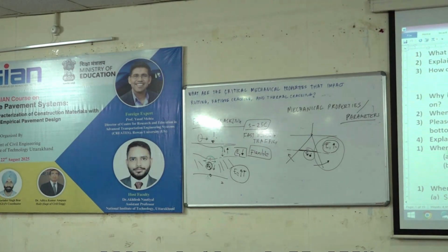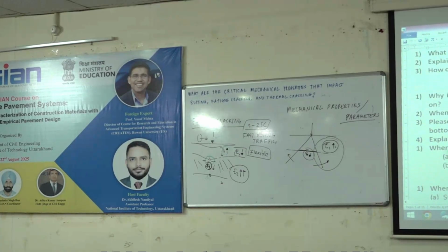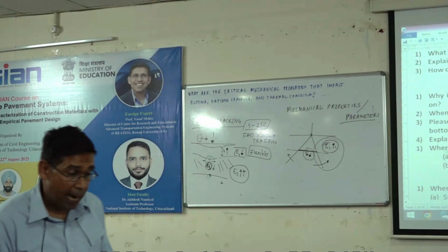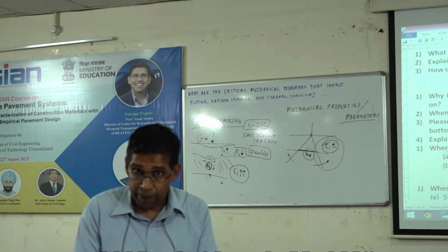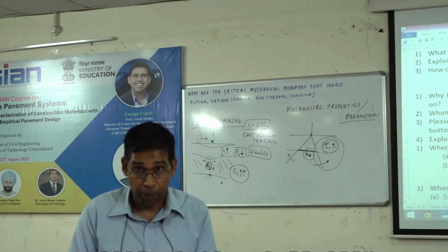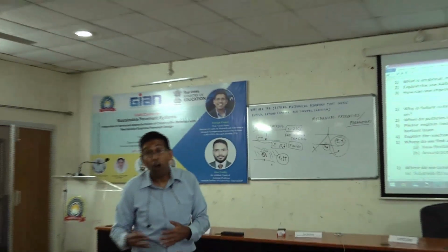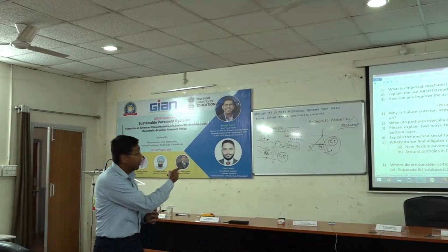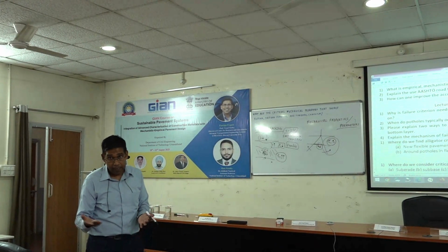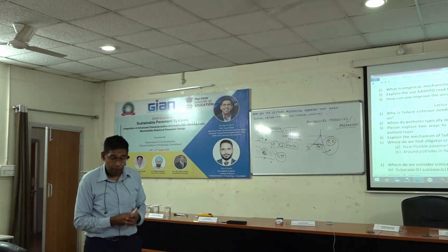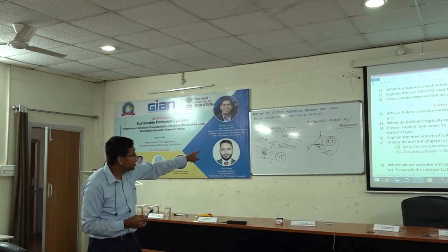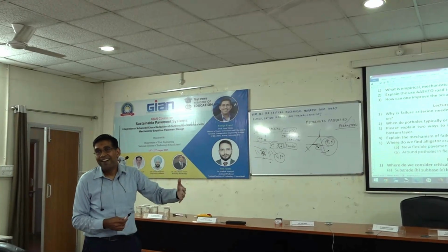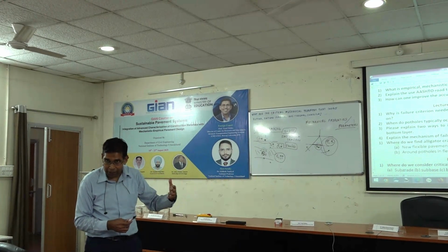Is there any correlation between the modulus of elasticity and the cost associated? Oh, 100%. Yes, because you have to make it angular, like you're going to ask on site, right? Angular, polymer modified bitumen, compaction. It's all about cost, right? Somebody mentioned polymer modified binder. That's expensive, right? Those cost money. So anytime you increase your E value, there is a cost. Anytime you increase your H value, there is a cost, right?